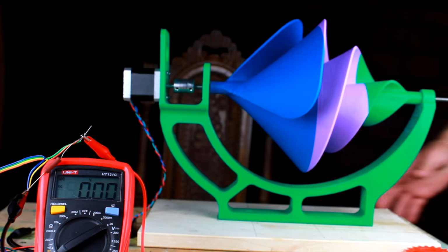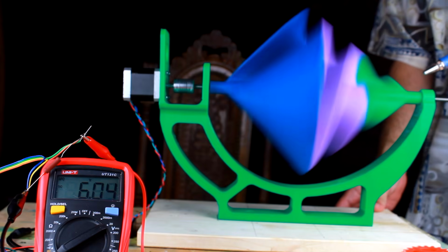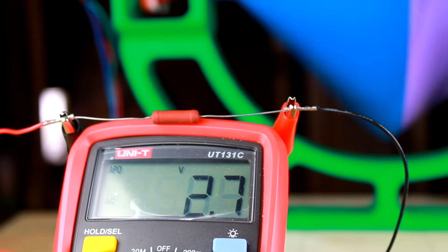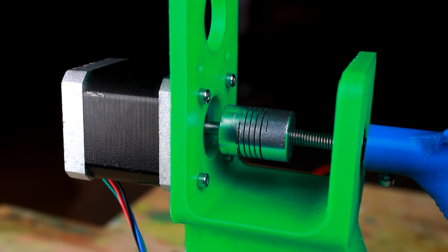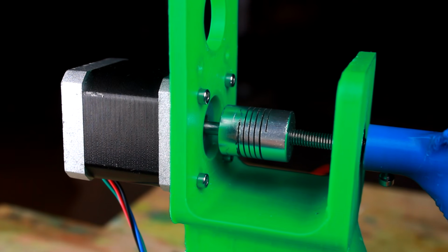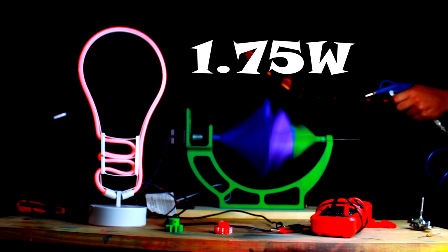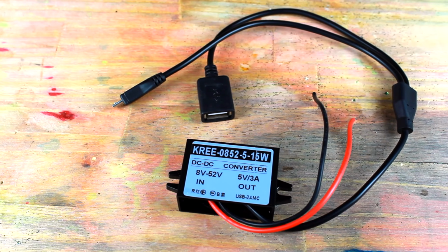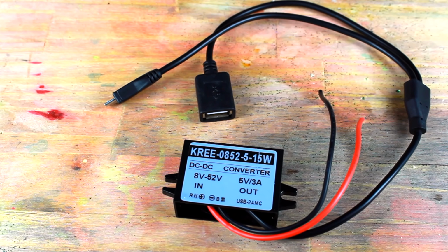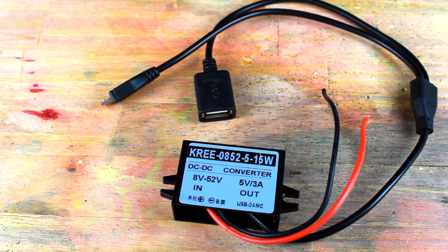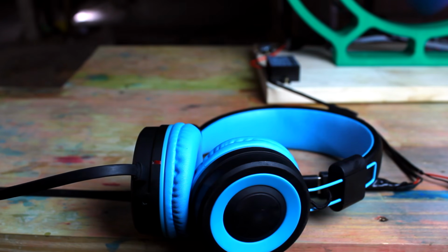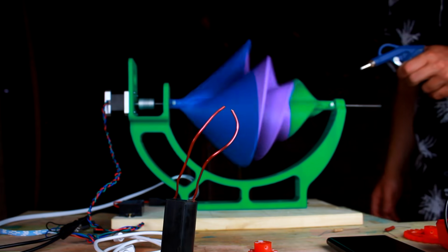With the new turbine ready, it was time to run some tests. I used my compressor to test the turbine using the direct drive and the geared one. I used a load of 57 ohms, and the option that resulted in the higher power output was the direct drive one, with 1.75 watts. It's not an enormous amount of power, but after coupling a power converter to the system that stepped down the voltage to 5 volts and increased the current, I could now charge my headphones, my phone, and a small spark generator. I'm not gonna lie, I was pretty proud of how the turbine turned out.